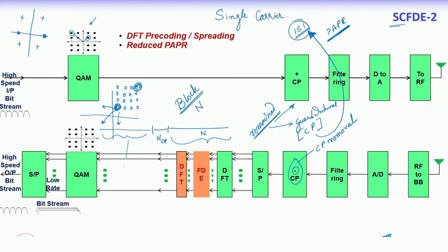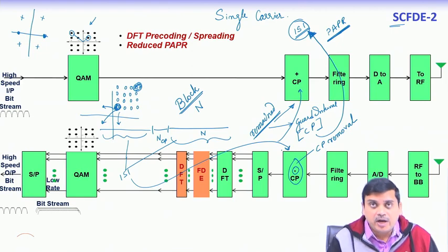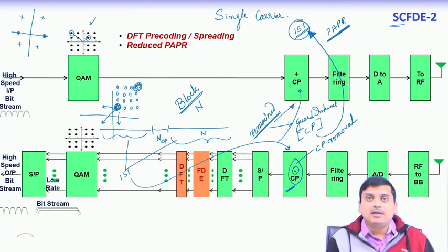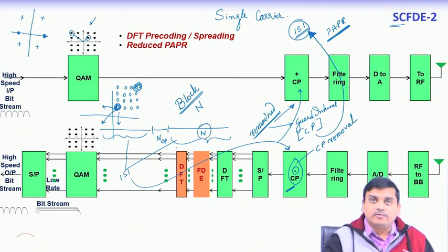Okay. So, the ISI between this and this is addressed by the CP that is added and the one that is removed. Now, one would argue that one has to apply ISI cancellation, but look at this, since we have got this CP, right, our earlier discussion that linear convolution in the time domain gets translated to circular convolution in the time domain. That means, if we do a DFT operation, it would appear to be the DFT of the channel coefficient matrix multiplied by that of the DFT of the received signal, all with n point DFT. This is something we have to remember, right.